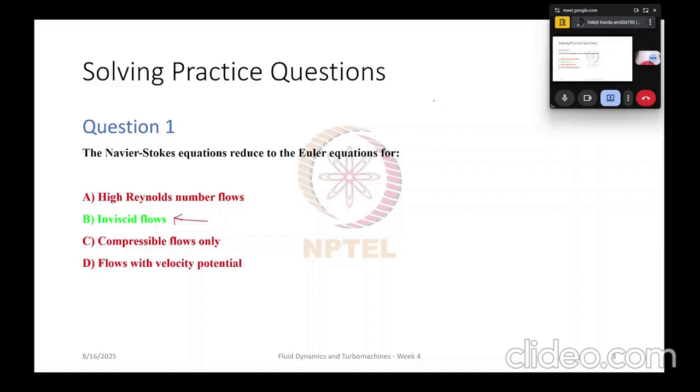So if we use a different coordinate system instead of the traditional XYZ rectangular Cartesian coordinate system, let's say we have a streamline like this, so if we fix our coordinate system along the streamline, calling this the streamwise direction, and we write down the Navier-Stokes equations in the streamwise direction, then it can be written in a way like this.